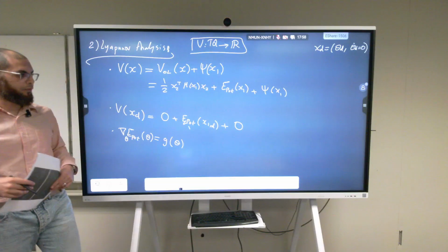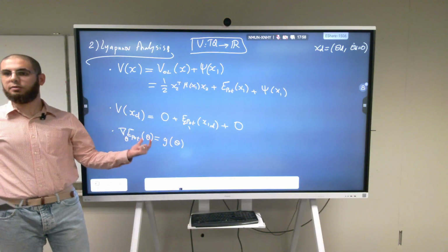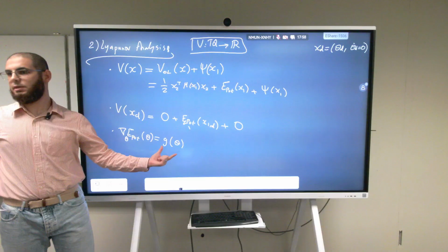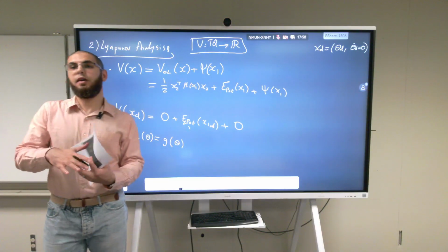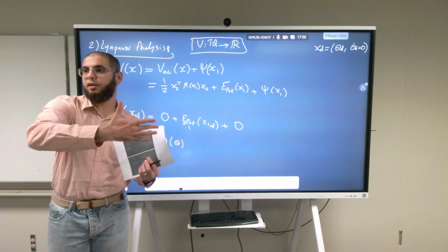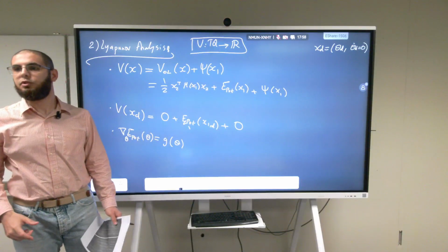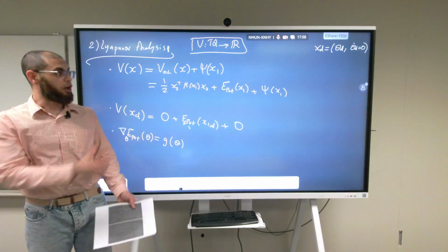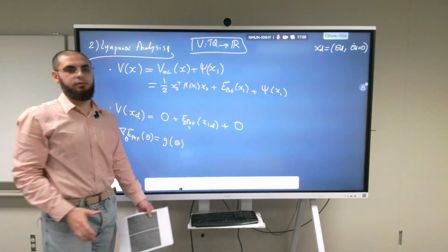So for this to be equal to 0, theta desired should be one of the equilibrium points of the system itself. So in general, if I want the robot arm to have a configuration that's not one of the equilibrium points, it's not possible to choose this Lyapunov function. It's not actually a valid Lyapunov function. In other words, this potential function that I added is not enough.